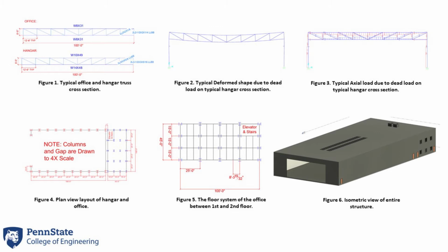To make this SAP model, the team had to first perform load calculations to find what forces would be acting on the system. This includes dead, live, crane, wind, and seismic. The values for what load values were used can be seen in the team's report. Next, the model was created in CAD and then transferred over to SAP, and these loads were put on the model. Lastly, the forces, axial, shear, and moment were pulled from the SAP model to be used in Phase 3 of design.